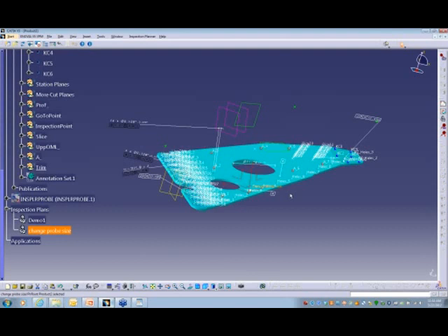Yes, in that probe builder, you can create them. Typically, all you guys that run a CMM know the PH10 or PH9 doesn't change. You put a different extension before the TP20 or the TP2, a 2-inch one, a 4-inch one, or an 8-inch one, and then you change the probe tip size. There's only a couple pieces that change. I've been running the CMM for 25 years, and typically each guy has maybe 4 or 5 configurations that they use. So you could build all these and save them inside the V5 Planner library and call them up anytime you want. Another very good question.